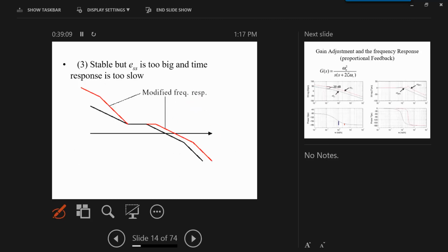In a complete system, sometimes you need a PID controller, a controller to address the low frequency, a controller to address the high frequency, and therefore you want to shape the response at the low frequency and at the medium frequency, and you modify basically the frequency response the way you see it here. And this is what we call the frequency response shaping.